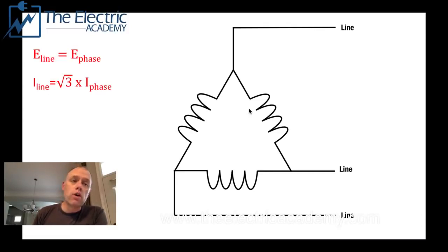Some motors, just as a note, will have these soft starters. They're going to start a motor in Y, and then they'll move it up to delta, because you've got a lower current in Y and a higher current in delta. So they call them soft starts, a Y delta soft starter. Again, maybe I'll do a video on Y delta soft starters later on in the year. So that's just generally a quick overview of what they do and what the systems are.